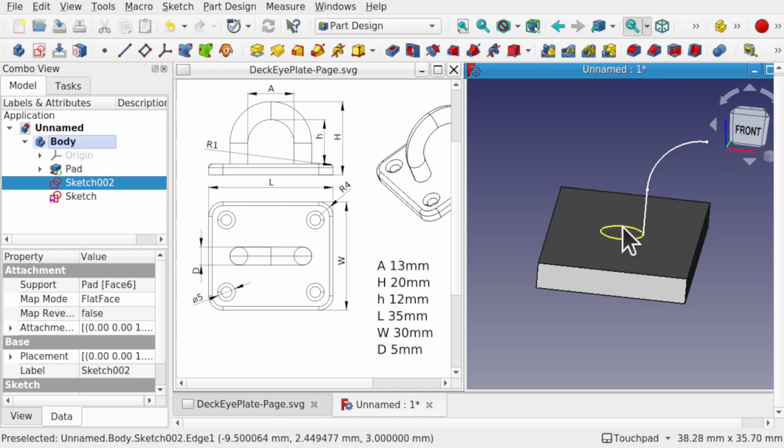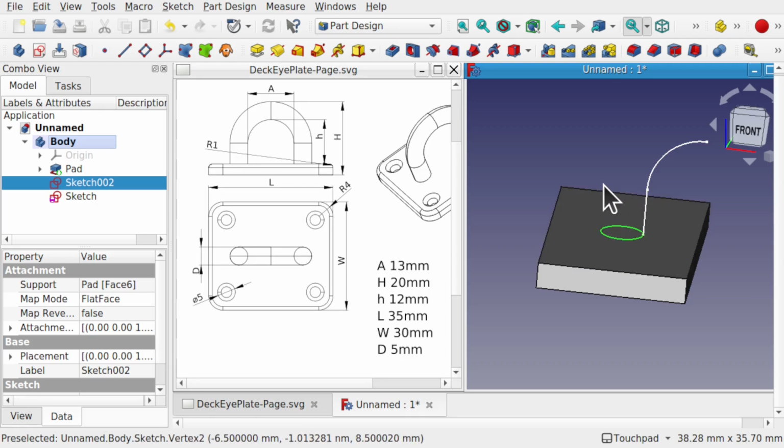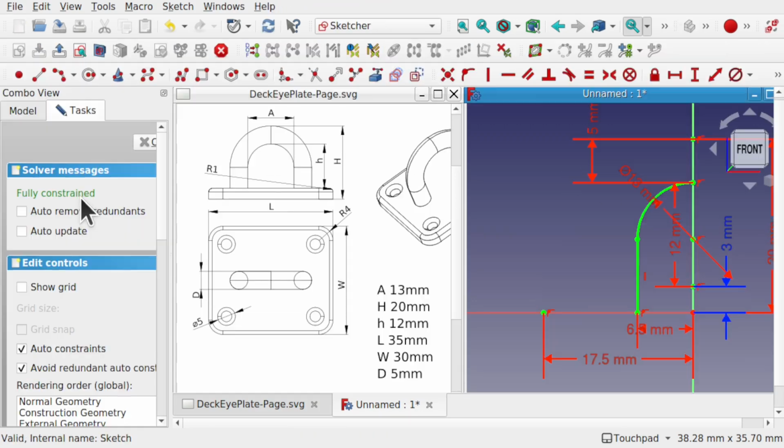Now what I suggest doing is taking this profile, raising it up to be in line with this point. And then we can pad to this surface and then use the same profile to revolve around this arc. Let me show you how that's done. We first need to understand how far away from the base the profile needs to be. So let's come into our reference sketch, and we've got this length here. And if you look, we've taken account the height of the base here.